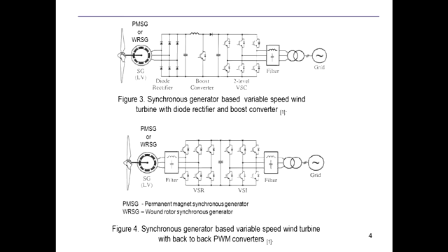And the control of this inverter can also be made such that we can feed real power and reactive power to the grid. Okay, when you feed reactive power to the grid, it affects the voltage, all right? And when you put real power, it affects the frequency and so on. So you may have to inject both real power and reactive power, depending on what the system impedance is. So controlling this converter with a certain real power and reactive power reference to put to the grid is something we will look at, all right?